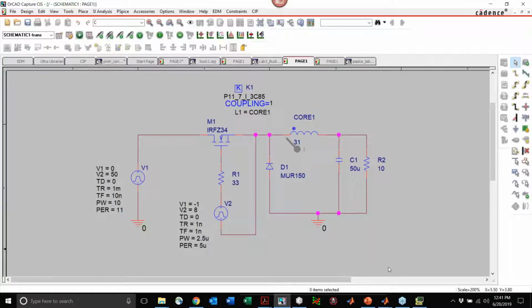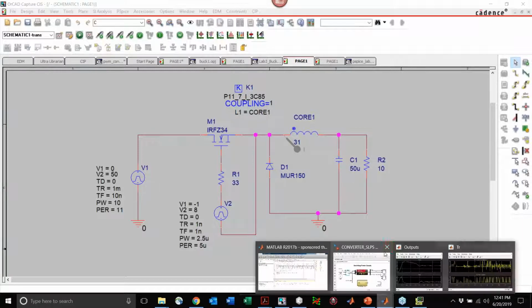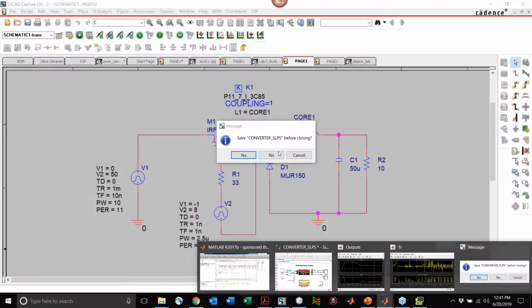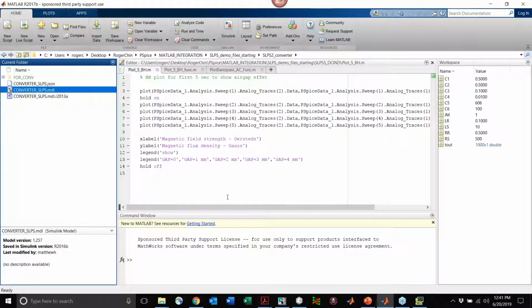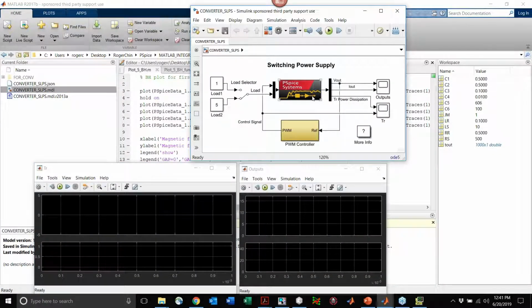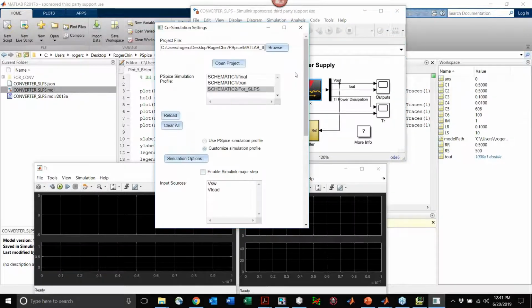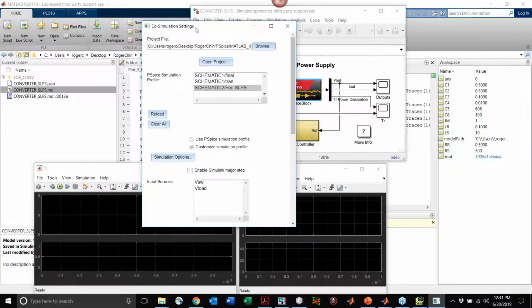And then, as I mentioned, you guys will often find that you have other models to tie in. Let me show you my MATLAB co-simulation. With PSpice, we can co-simulate our model or SPICE circuitry that we build with other models. What I've done here is we've taken a converter topology and built it into SPICE. If you guys aren't familiar with the SPICE block here, what you do is you simply assign the voltages that you're going to replace using the MATLAB models.